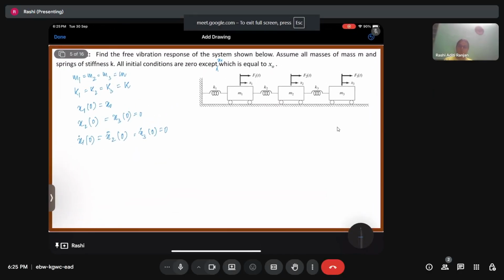Similar is what we are going to do over here. We are going to first find the three natural frequencies, then find the three corresponding eigenvalues, and then using those eigenvalues and eigenfrequencies, we are going to find the general solution. We will write down the linear combination of these three as the solution, and then we are going to put time equal to 0.